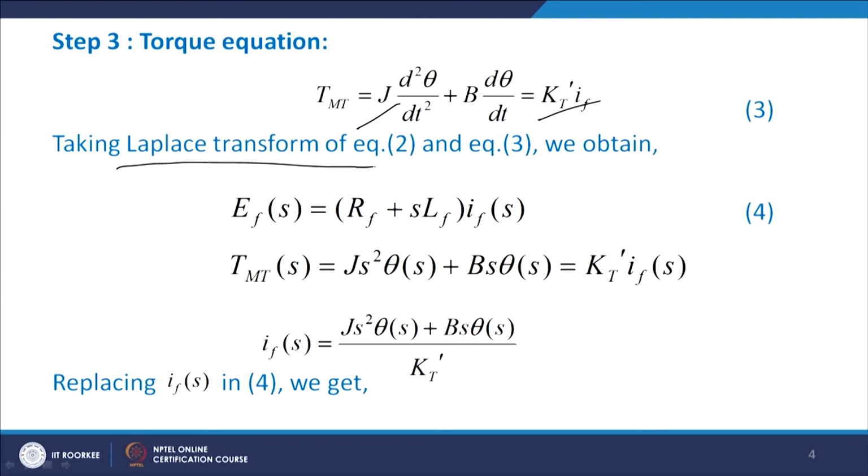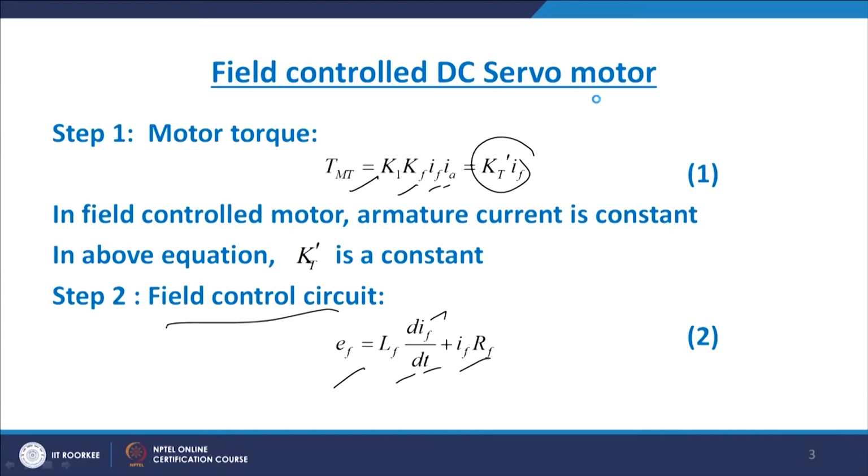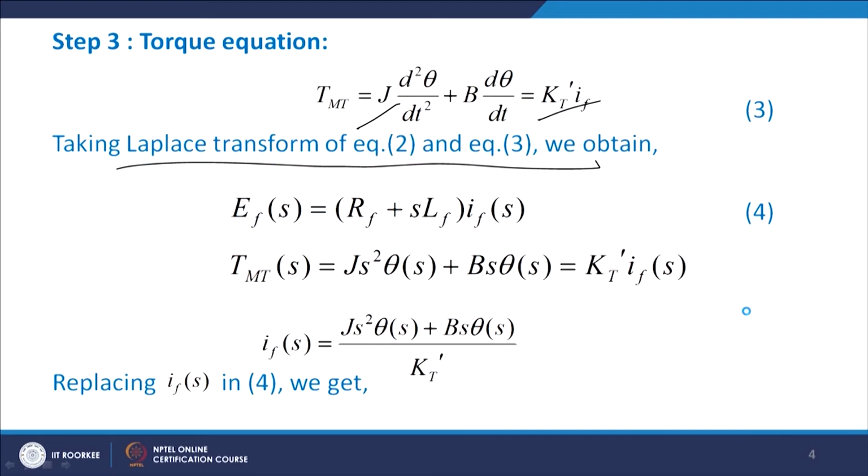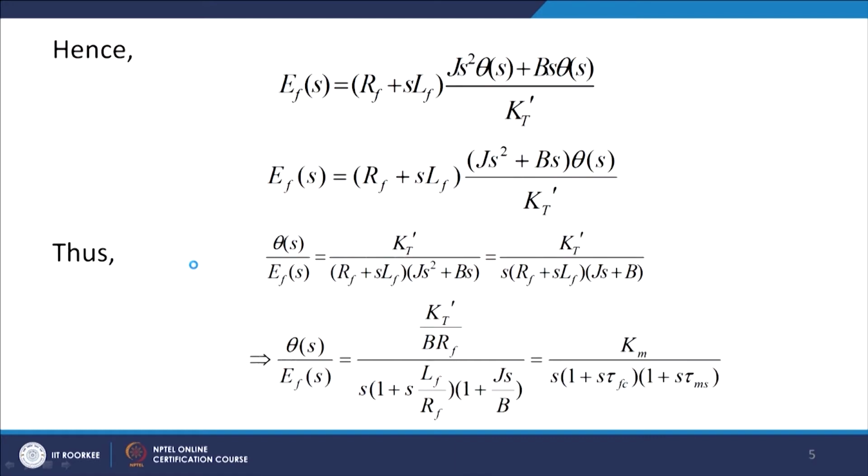So we have got the equations in the time domain, but we want them in the S domain. Therefore, we apply the Laplace transform to equations 2 and 3, and we got this. Now from this expression, If(S) is written like this, and replacing If(S) in equation 4, we got this result.